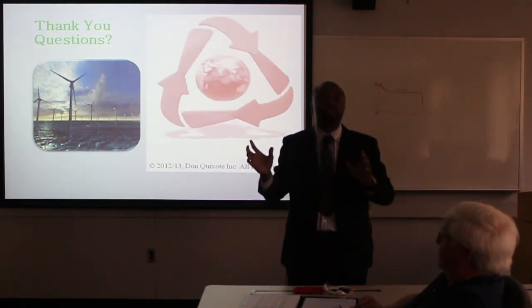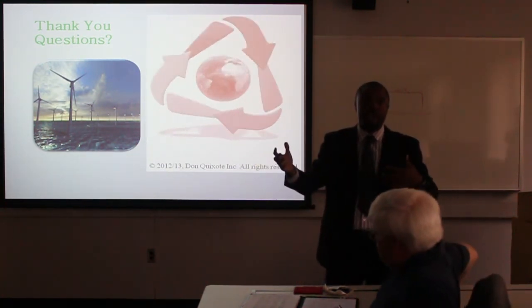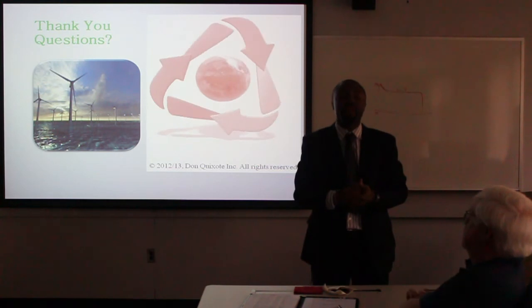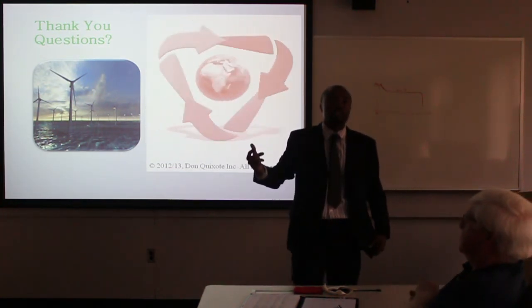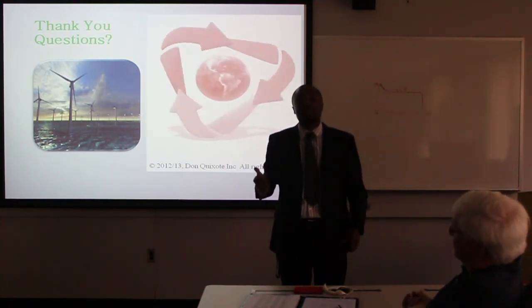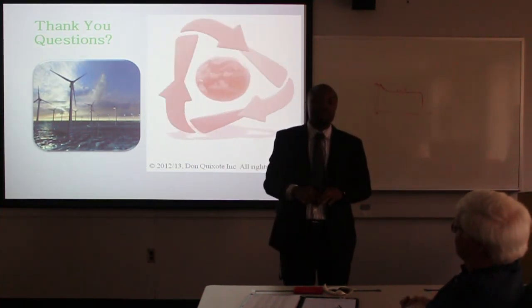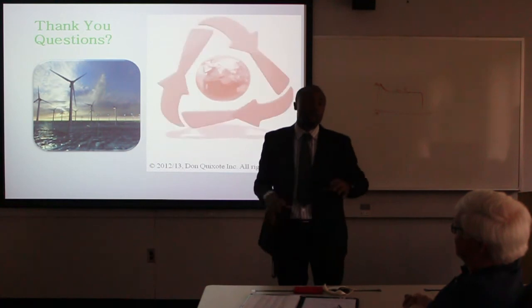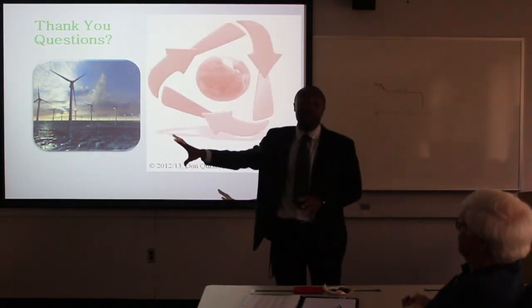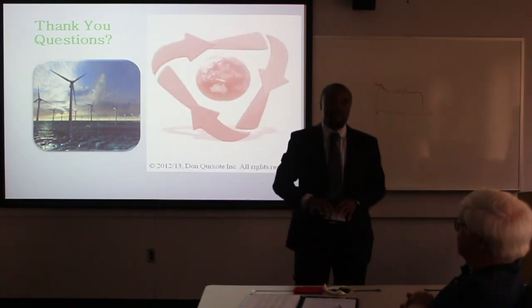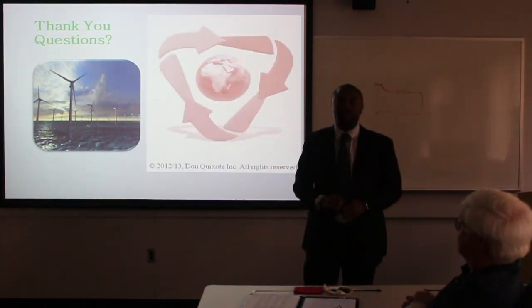So we used that wind speed to calculate the force that was produced on the turbine. If you want to go higher, you have to go through the calculation and get the force, the torque, and the speed of the motor necessary to get back to stability. So you cannot just take this for 50 or 60 miles per hour and expect the same result. Our design was based on a wind speed of 25 miles per hour.